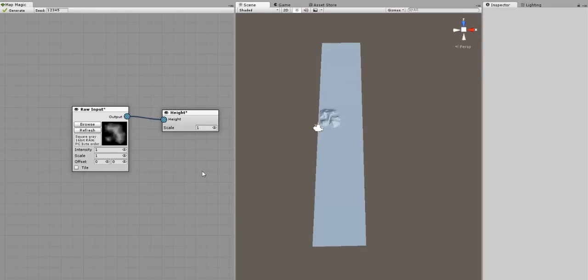Now let's scale our island to make it fill all of the planned area. Since it should be scaled 10 times, we will set the scale in row input to 10. And since the center of the terrain should be placed at the 0 coordinate, we will make an offset of -5 kilometers on both axes. Let's wait a bit while it processes all of the 20 terrains.